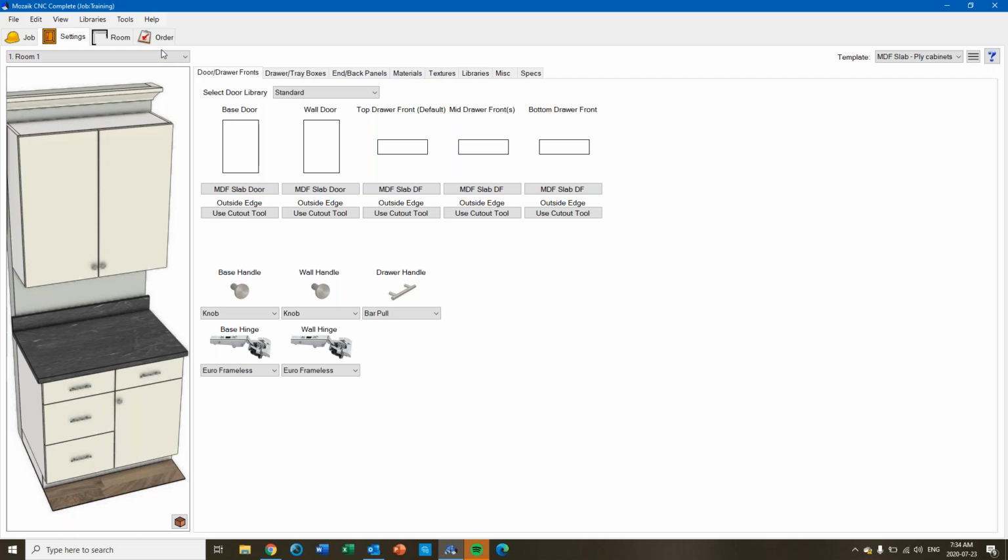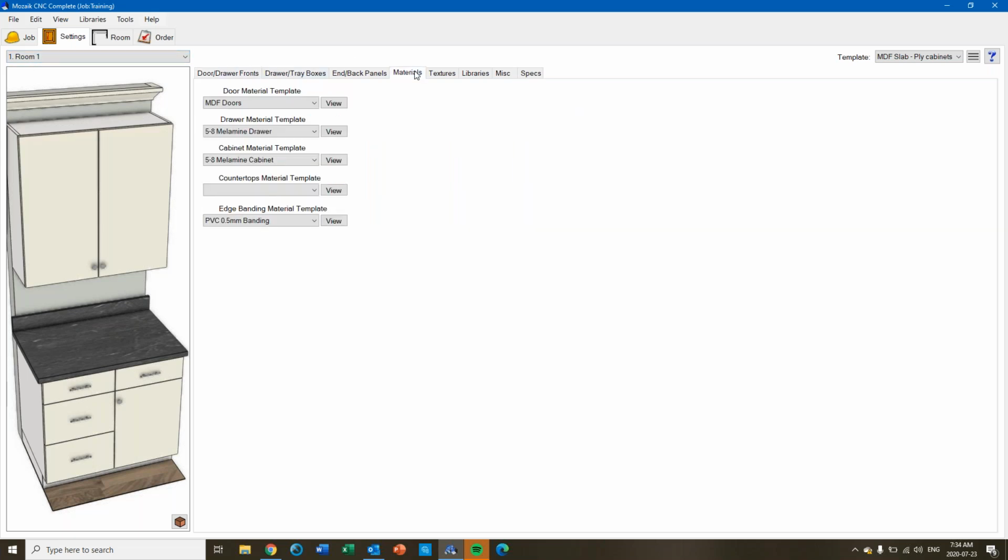So parameters are per job. The first thing you gotta realize is the problem is not anything to do with parameters. You're getting their parameters, which are how a cabinet is built, and they go with the job. But what you won't get is their materials. So you and all of your shops that you work with have to be on the same page. Perhaps you're going to need to make a whole bunch of material templates and provide them to them,